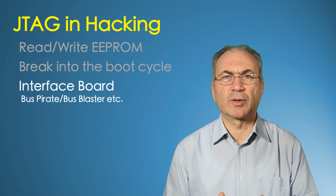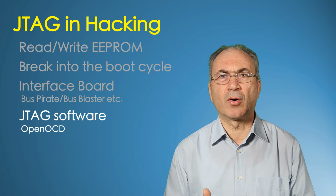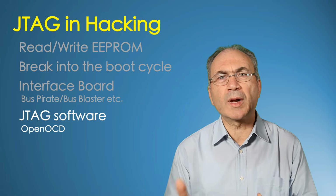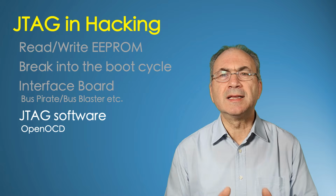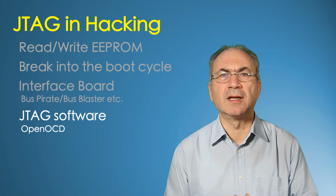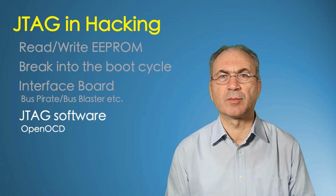We also need the software to interact with the interface boards and the JTAG itself, to dump the EEPROM content or to enable in-circuit debugging. The most popular software in the open source world is OpenOCD. You will find the link in the description below.